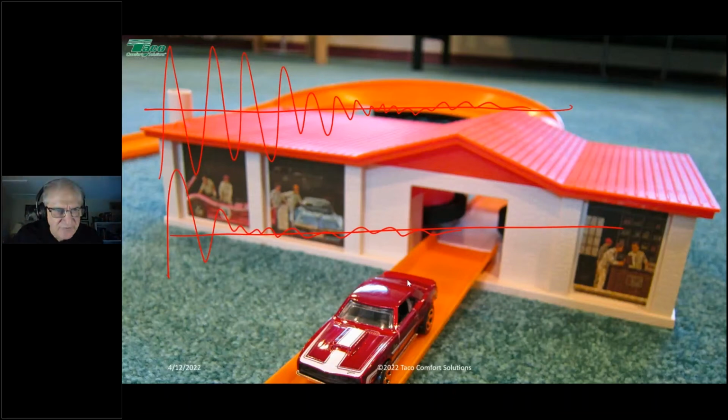Okay. Is valve authority important for other types of control valves, or does it depend on the valve type? For example, would it be important on a throttling valve? Any kind of valve where the position of that valve is electronically moved, that's kind of what we're looking for. Again, a motorized mixing valve is the one that I pay the most attention to. So I think that's really where you want to pay attention.